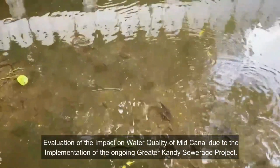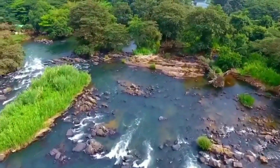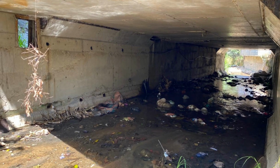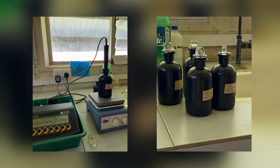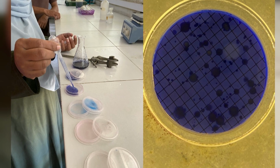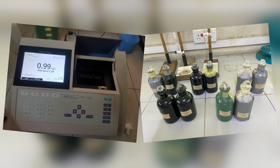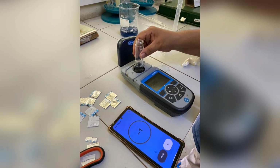The Mid-Canal in Kandy is a highly polluted stream that flows into the main drinking water source of the city, Mahaweli River. To improve its water quality, the efficiency of the Greater Kandy Sewerage Project's collection system was assessed by measuring key parameters like pH, BOD5, fecal coliforms, and others across various locations during wet and dry periods. Despite ongoing efforts, the analysis revealed that the water quality of the Mid-Canal remains poor, as confirmed by the Water Quality Index developed through this research.